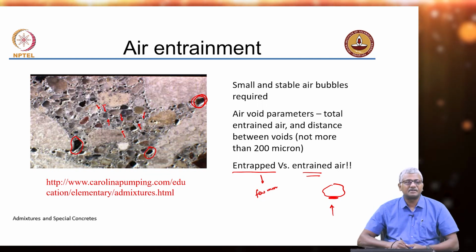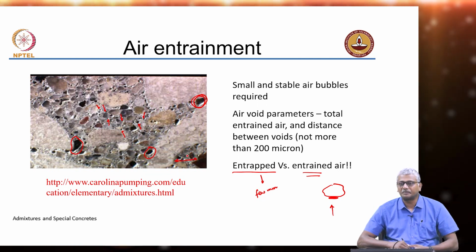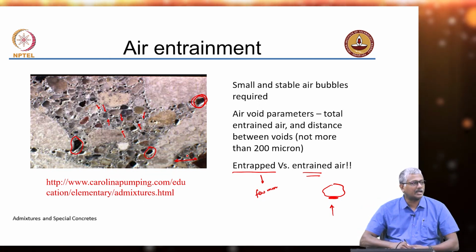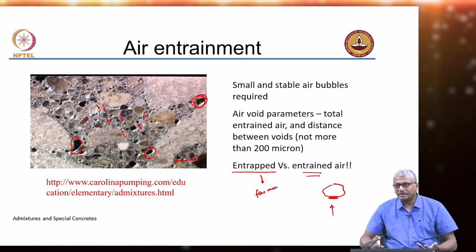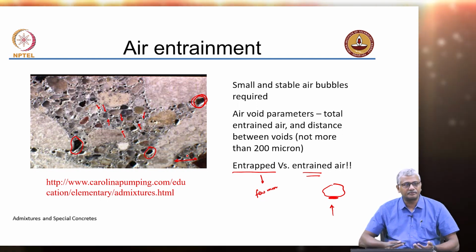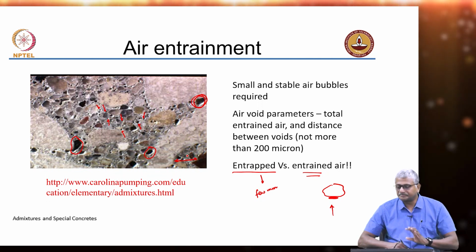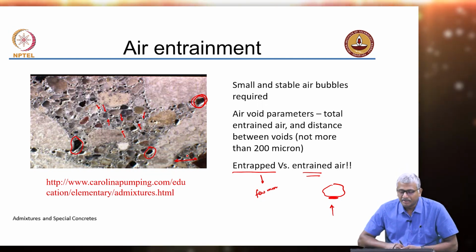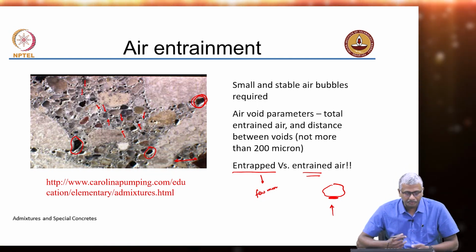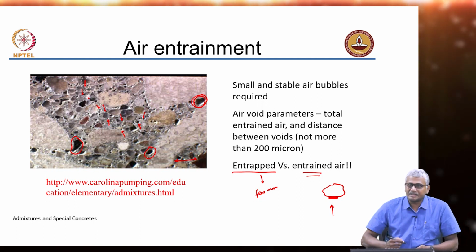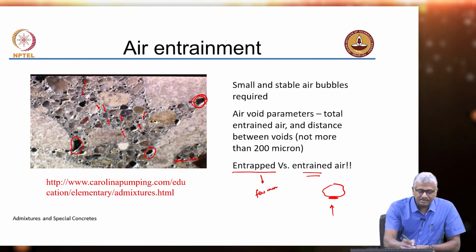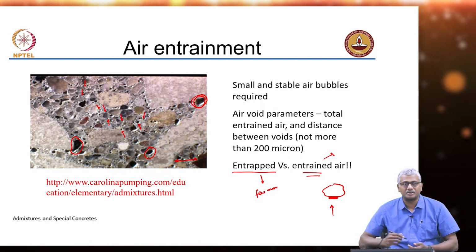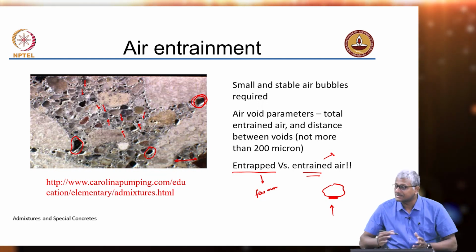You might have seen this with lime, right? Slaking of lime. We typically add water to calcium oxide, and there is a massive heat evolution from that process. Same thing even here in cement, there is an exothermic process which releases heat. Of course, in terms of crystal structures, this is not the right platform for the discussion, but yes, several crystal structures are possible with C3S. And as we were talking earlier, alite is nothing but impure C3S, which has other impurities. Some of the impurities are provided here just for your understanding. We are not really going to discuss this in more detail.